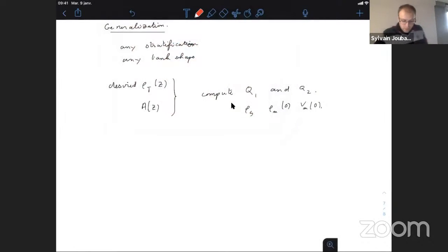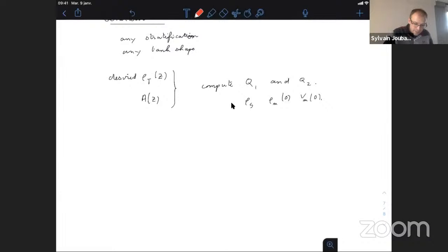So that was the first thing, the double bucket method that we use every day in laboratory experiments, and that's how we implement it. And that's the first thing master students and PhD students learn when they arrive in the lab: how to make a nice stratification. When they know that, you can do experiments. If you don't know how to make a nice stratification, that's complicated. So that's the first thing you need to learn, how to make a good stratification.